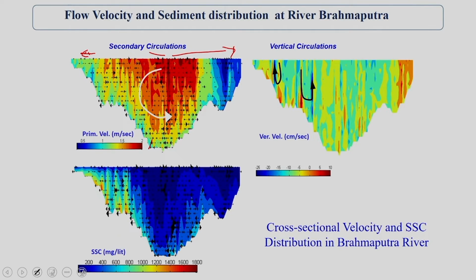So if you look at the scour zone, the velocity is about 2 meters per second, but there are reaches where the velocity is less than 0.3 meters per second, 1 foot per second. But there are reaches where the velocity is more than 2 meters per second. That means the velocity varies from 0.3 to 2 meters per second, almost 10 times, within these cross sections.